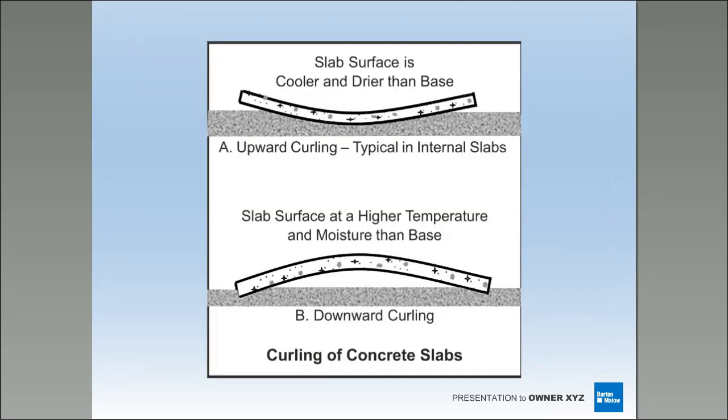So here's a prime example of that picture you just saw slide back. If you look at the panel edge, see how they're curling up? If I put those four panels together, there's my curl right there. As a polisher, you've got a planetary grinder coming in here, and you're going to cut across this thing nice and flat. If I have curl in these areas, I'm going to have the cut I want out here, and I'm going to have the cut I don't desire at every panel corner. It can also happen on some of the panel edges. It can happen here on a slab with curl, typically at the intersections when you're starting to get an abundance of curl.